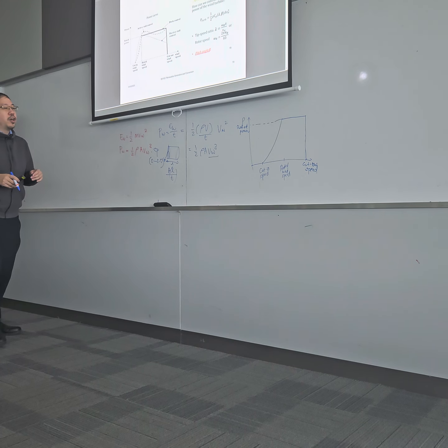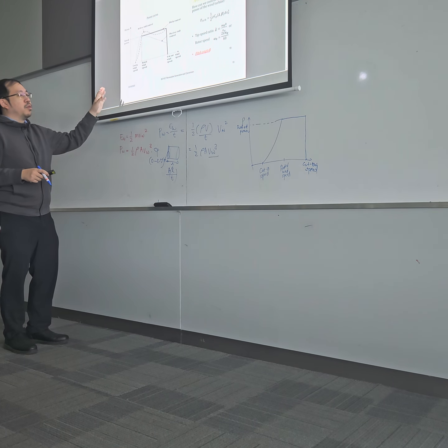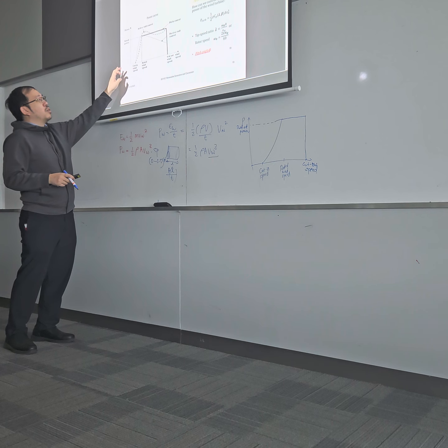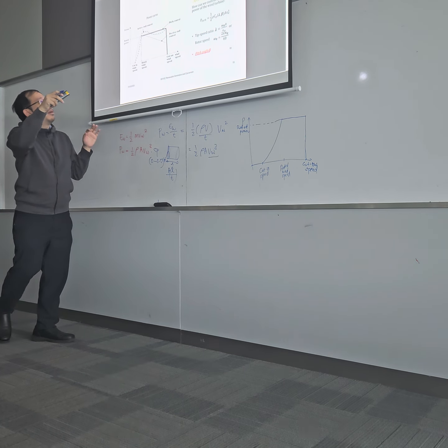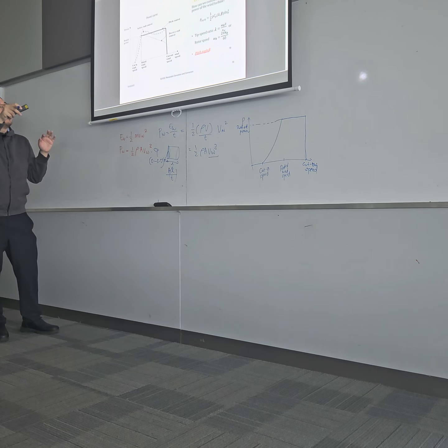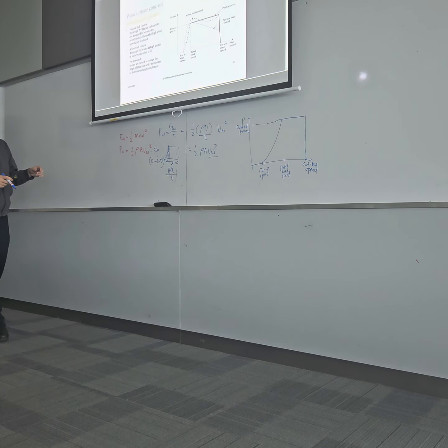Alright, and if you are required to plot, you need to be able to differentiate both. This is the wind power curve, and then the three power control strategies: active stall control, pitch control, and passive stall control, which are explained in this slide. Okay, all there. Both questions have come up before. One question on the wind power curve, and then one question on the wind turbine controls. Both have been asked before, but it's usually either or. They will not ask both.